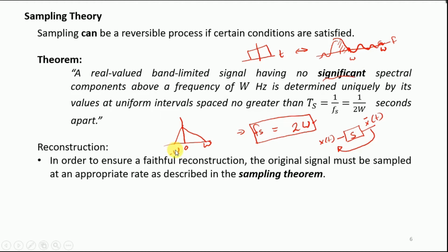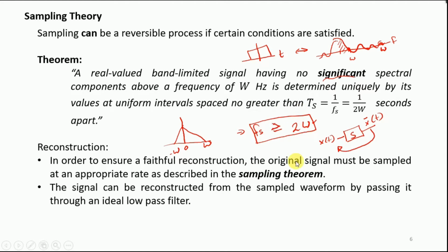For reconstruction, first and foremost you must satisfy this condition, that is the Nyquist criterion. Next, we would use a low pass filter to recover back our original signal. I would discuss this next as well.